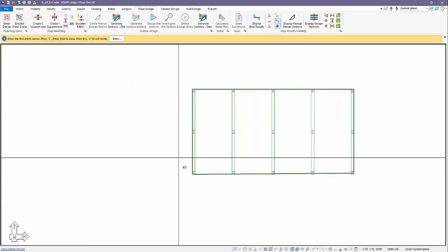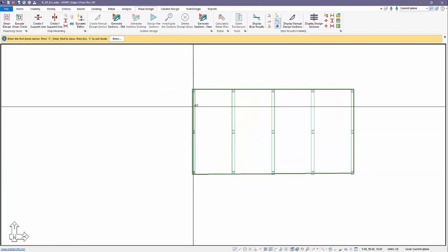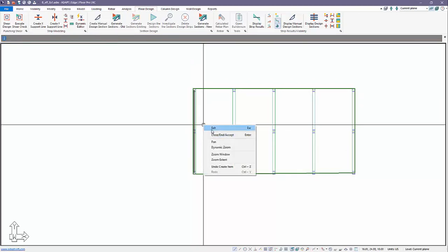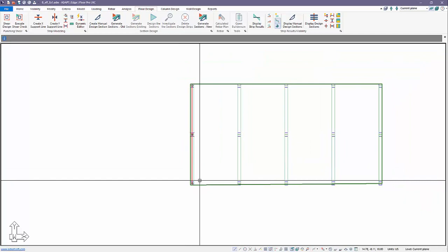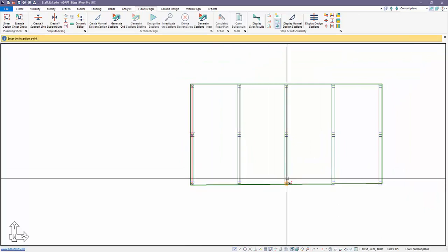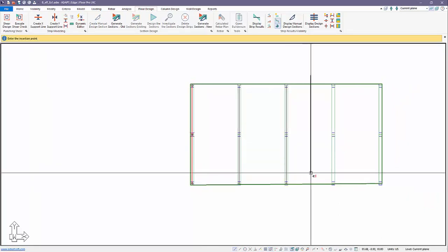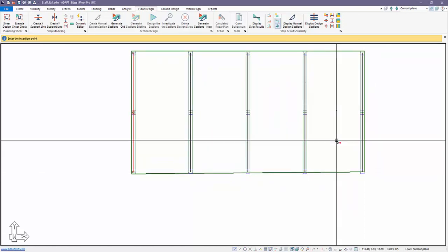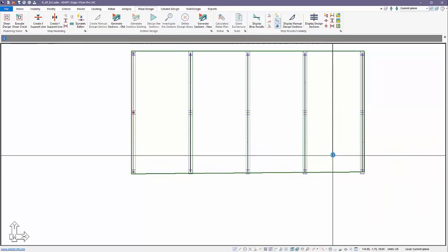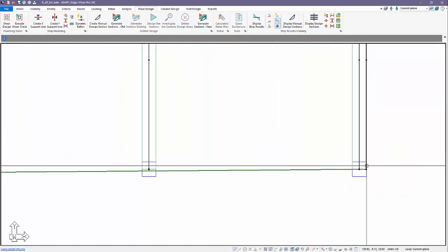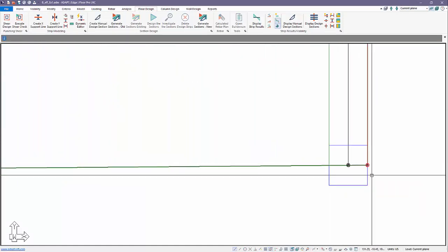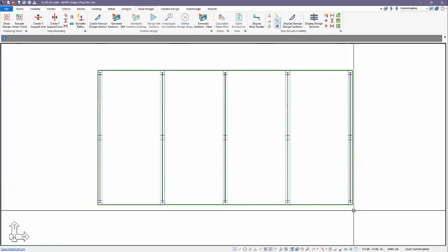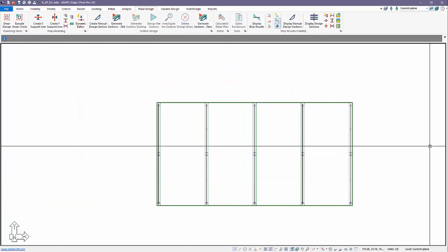Okay, and we're going to go in and just model support lines on these beams. So I'll just model one support line. I'll copy that support line over for each of the beams. Notice I'm not needing to extend these to the slab edge. The new features in version 19 do not require that, so there's some new improvements there as well. And here we have a series of beams.